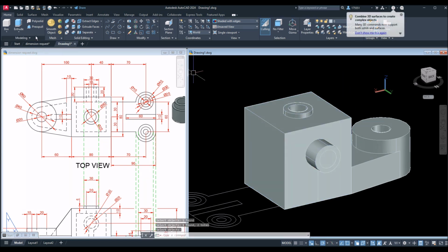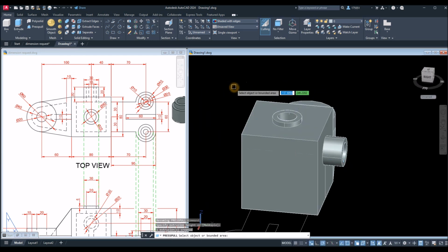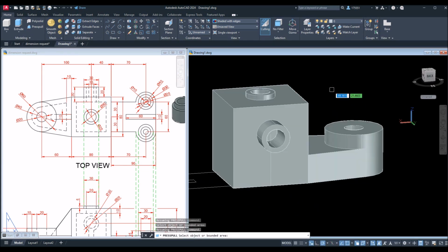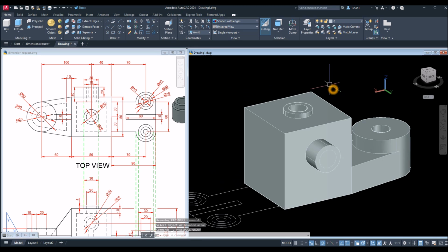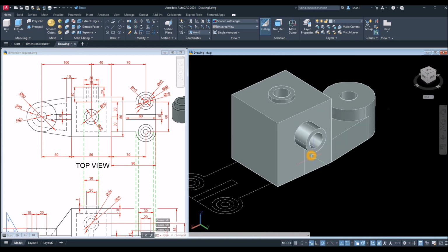This one, and poke a hole through here. So press pull command, hover over this center, left click, and just snap this. Don't go through here because now it's one object. Then you can create a hole here. See, if I do that, see the hole went all the way through the object. So if I undo, so press pull, hover over, left click, let go, and just snap this center here. Now we're safe.